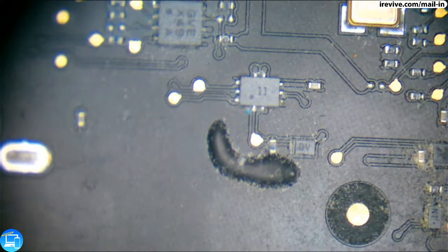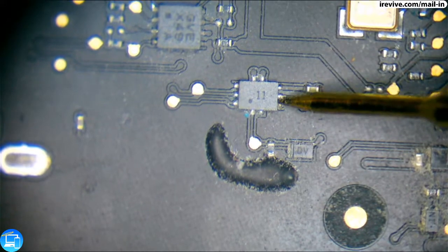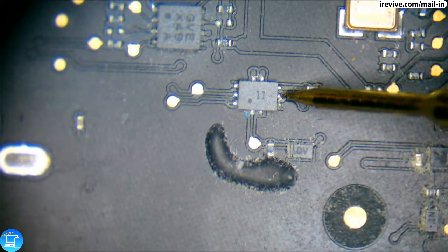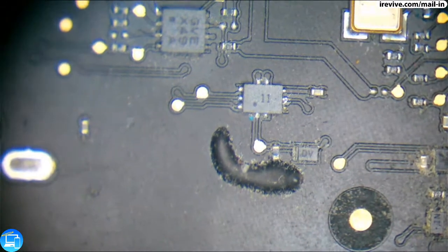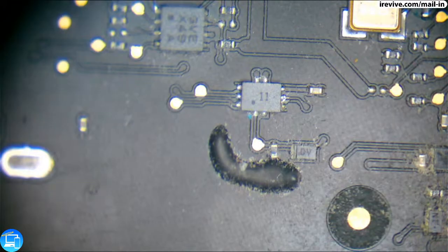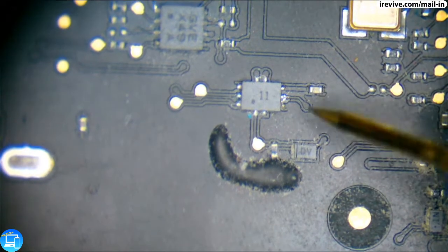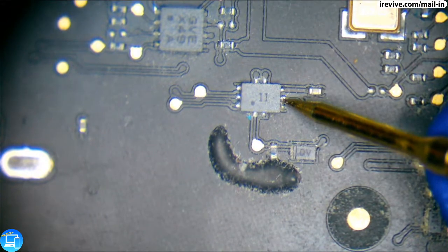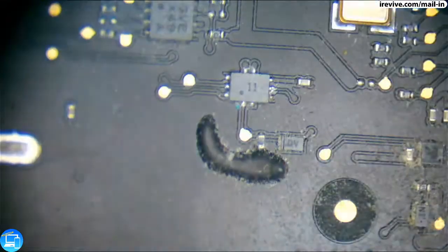Alright, let's see what we have right here. PM Sleep S4 is missing. Okay. So something seems to be going on here. Let's take a look at the solder balls underneath the SMC. And doesn't look like there's necessarily any corrosion over on that side. Look fine here.